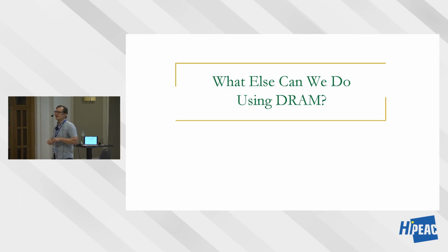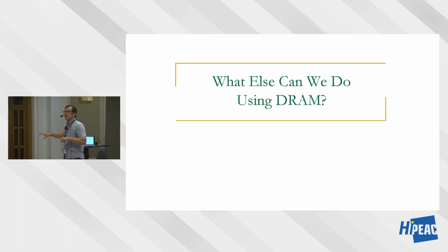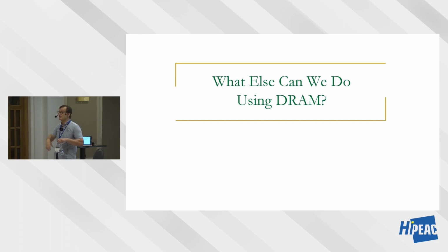But I think the effort to overcome that is changing the sense amplifier and changing the row decoder such that they're more robust in the way we're doing things. Right now, truly DRAM is not designed for this purpose, right? We're really violating the timing parameters so that we get a good timing to show these operations. Even these operations that we showed are not based on the perfect timings, right? If we actually do a complete sweep on the timing, we should be able to come up with a better operating point.